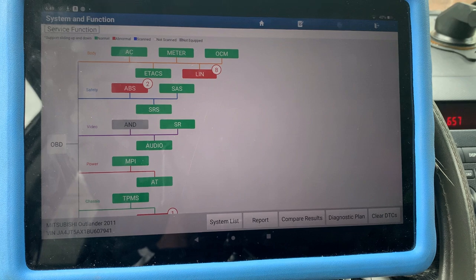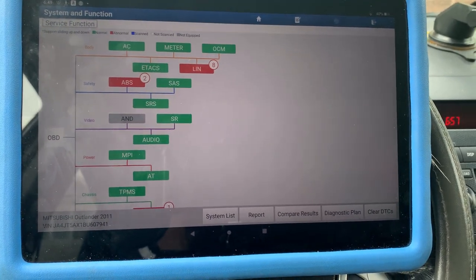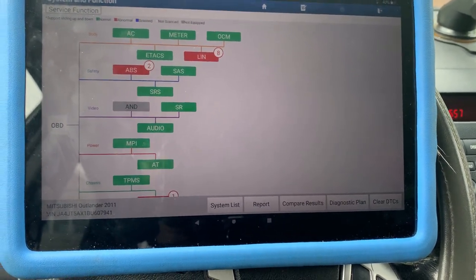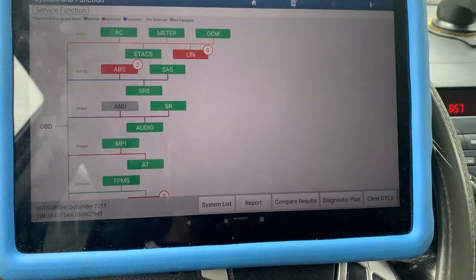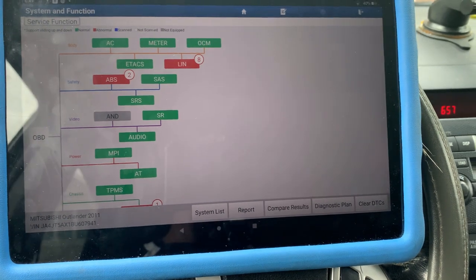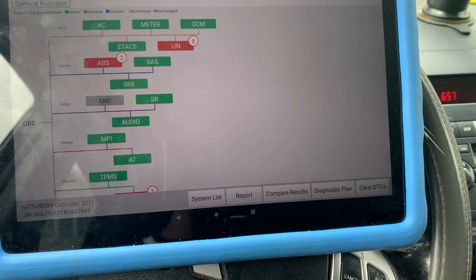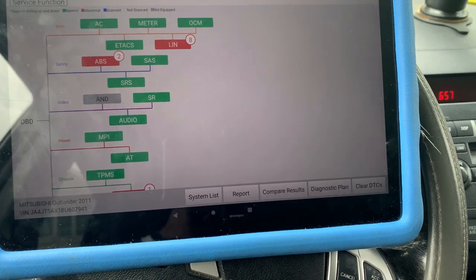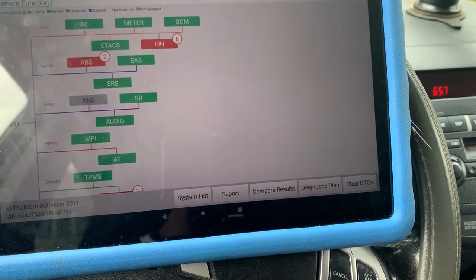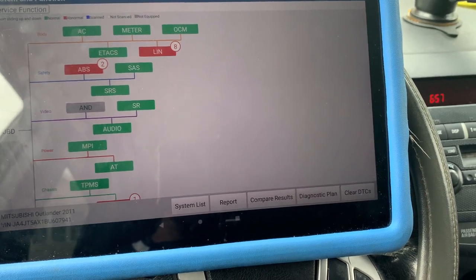I'm just going to unplug it, and I also tested the resistance of the blower. It showed like 1.2 kilo ohm, so I knew right away that the blower gave up. I'm just going to put this lamp on that blower connector, and we'll see if the light turns on or not. Yeah.